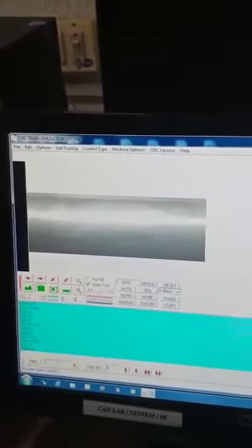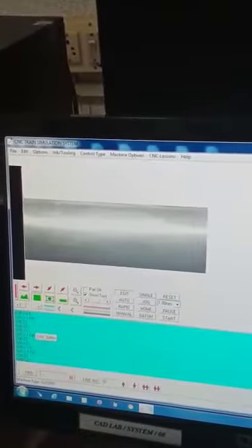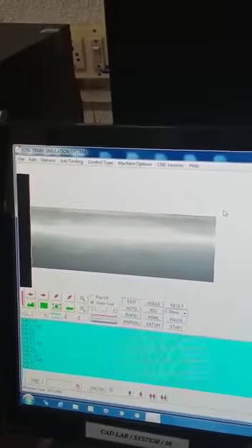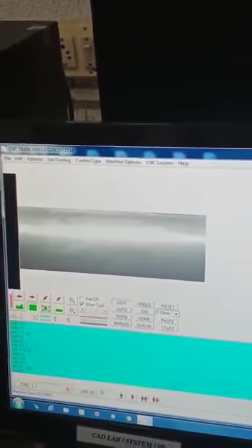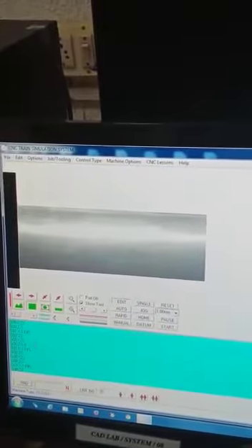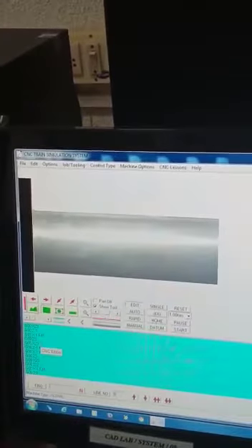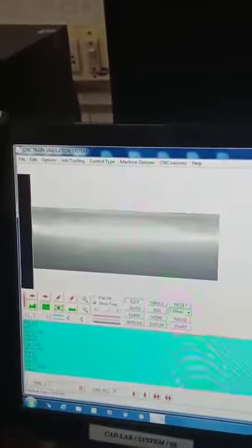Now you have to come to this, your G00 Z3. Now again it must go to your G00 X23, your initial position. Now again G01 X minus 1 F45. So again, of the 2 mm, this 1 mm must be reduced. So G00 Z3.